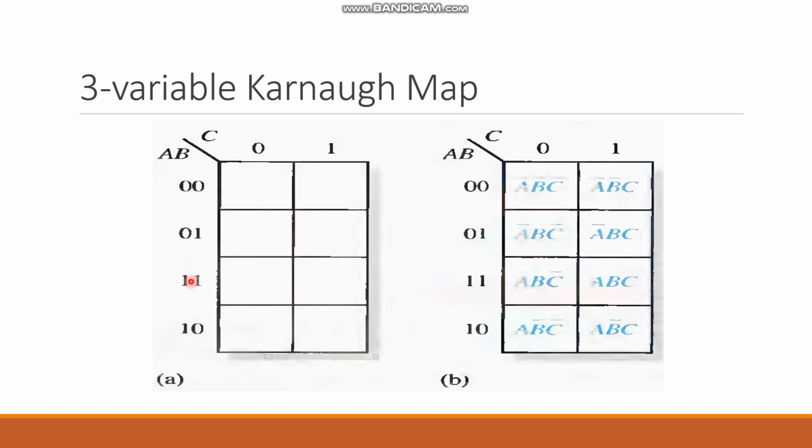In the normal way, instead of those two, we would put 10 here, because this is 0, 1, 2, and 3. But if we put 10 instead of those, what is going to happen? This is 1, this is 0, this is 0, this is 1. That means 2 bits are different from each other, and it doesn't follow the gray code rules. In the gray code rules, we say the adjacent values must have only 1 bit of difference. This is applied in what is called the gray code representation.